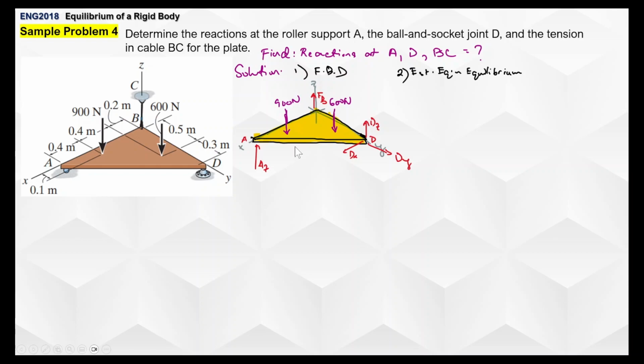Next step here is to establish equilibrium equations, and here we got a summation of forces around the x-axis muna, which is 0. Technically, dx lang naman yun, so dx is equal to 0. Automatically, there's no reaction there. But it makes sense, given the type of support that it's providing, the body will not move at all. So 0 yung forces dyan. No reaction at all. And then at the y-axis, summation of forces along the y-axis equals 0. And the only force in the y-axis is dy. So that's dy equals 0.